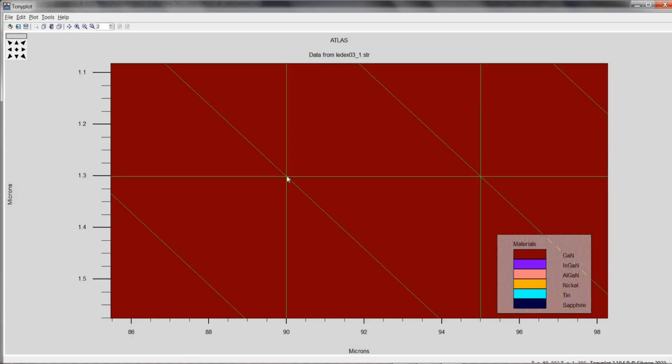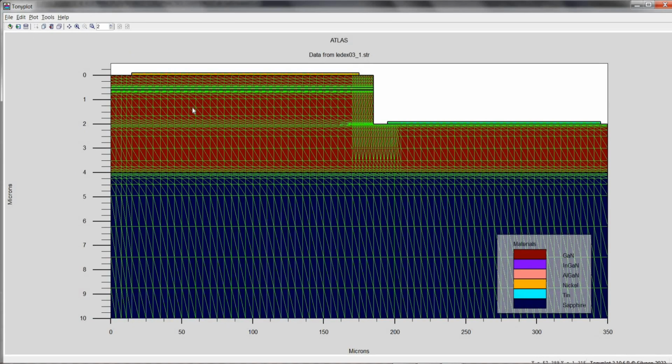So in Silvaco TCAD we can define a maximum of 20,000 points for our particular structure. Defining more points would result in a more accurate simulation of the structure. So what happens at the nodes?